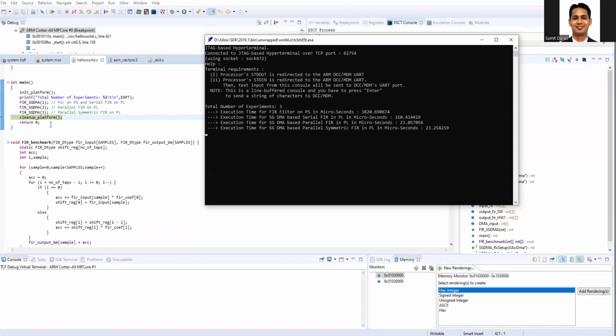When the coefficients are not fixed, you can add another input via a stream interface for inputting the filter coefficients also. Also, in this case, your FIR filter length is fixed. When the filter length is not fixed, how to design the corresponding FIR filter, those are the things you need to take into account.